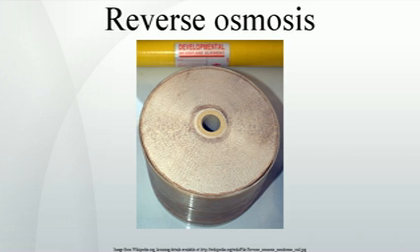Although this process has proved to be costly and not very convenient if it is intended to meet mineral demand by humans and plants, the very same mineral demand that freshwater sources provided previously. For instance, water from Israel's national water carrier typically contains dissolved Mg levels of 20 to 25 mg per liter. Water from the Ashkelon plant has no Mg. After farmers used this water, Mg deficiency symptoms appeared in crops, including tomatoes, basil, and flowers, and had to be remedied by fertilization. Current Israeli drinking water standards set a minimum Ca level of 20 mg per liter.